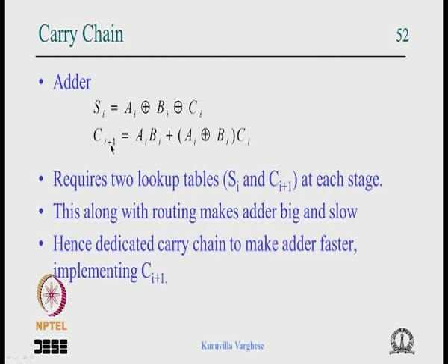That means the carry is generated if both inputs are 1, then you definitely know that the carry is generated. It does not matter whether the input carry is 1 or 0, because 1 plus 1 is 0 and the carry goes out, and even if the input carry is 1, the sum just becomes 1, it does not matter. And if both are not 1, if either of them is 1, then the carry out will depend on the carry input. If the carry input is 1, the carry output is 1. So that is what the equation says.